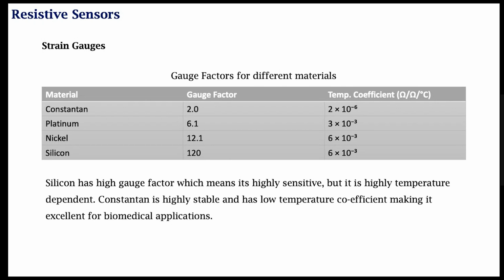Also, some of these devices have, for example, an array of strain gauges that measure strains or forces on a nail, for example, a wearable fingernail strain gauge array that detects and measures tactile forces during object manipulation with an excellent 50 microstrain resolution.